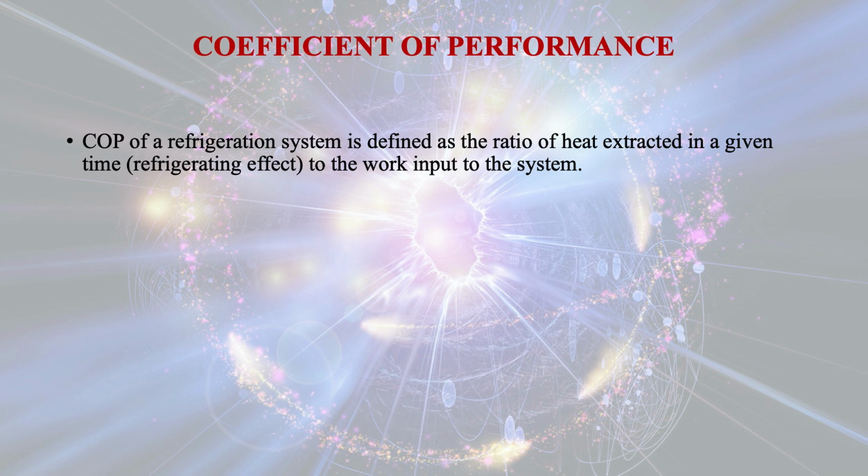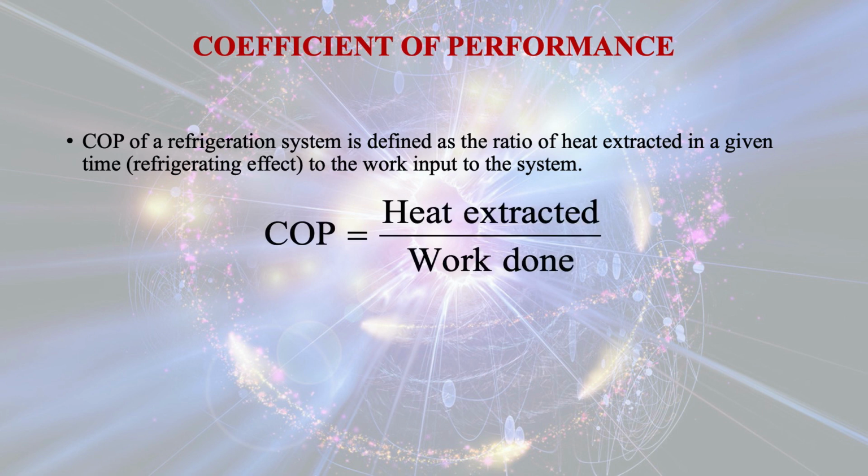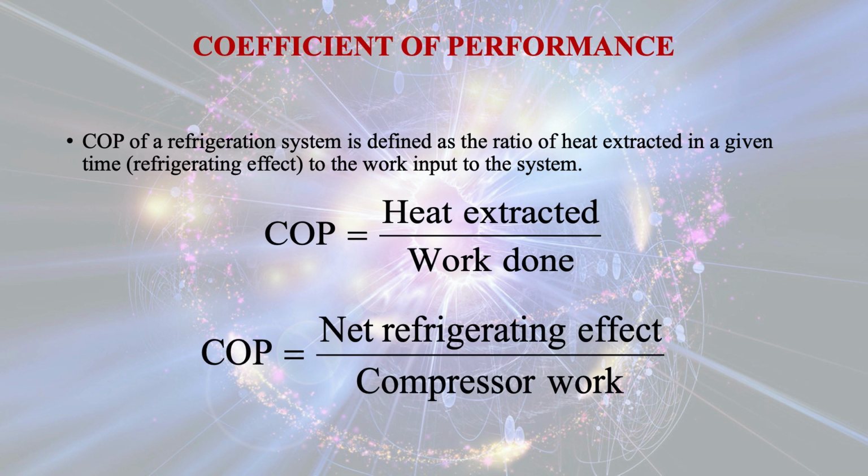Now let us talk about the coefficient of performance. Coefficient of performance of a refrigeration system is defined as the ratio of heat extracted in a given time, that is refrigeration effect, to the work input to the system. So COP is defined as heat extracted divided by the work done, or we can also say that COP of a refrigeration system is equal to the net refrigerating effect divided by the compressor work.